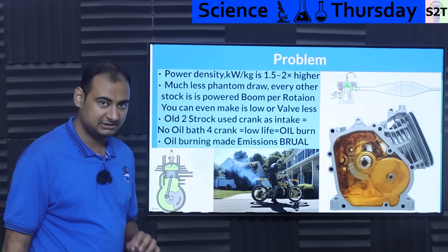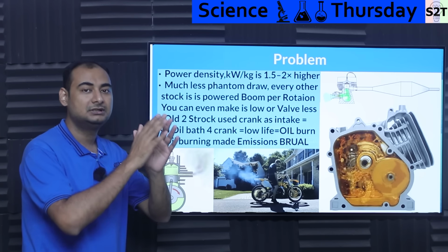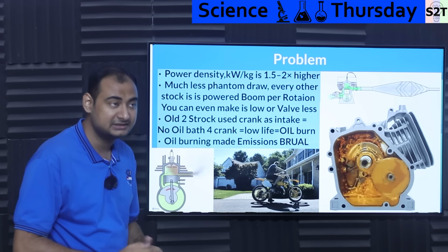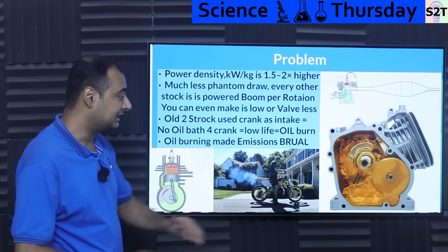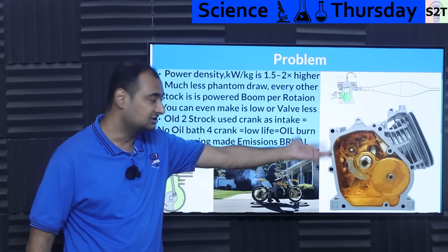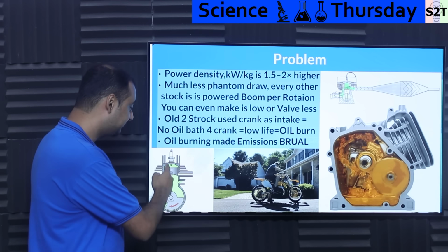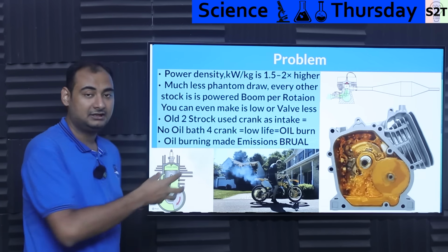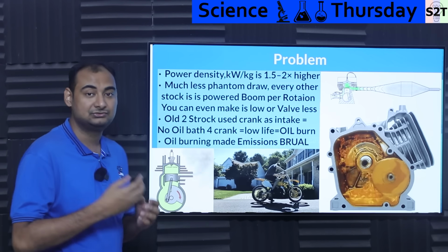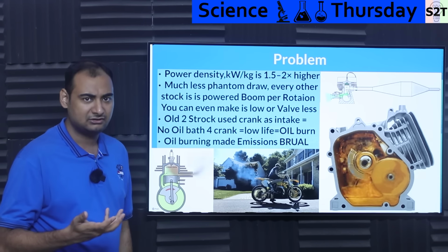The crankcase is not isolated. Four-stroke allows you to isolate the crankcase. Basically, everything below the piston, or specifically the piston ring, is independent, meaning you can have that puppy submerged in oil in four-stroke. What is the benefit? This puppy will last forever. The second penalty that you solve is that in two-stroke, because this area is getting swept by air, you have to use roller bearings, which you have to do anyway. Even with that, it will not last a very long time.